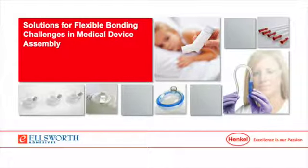For example, we have seen cyanoacrylates demonstrate an increase of beyond 30% of initial strength following 50 to 100 kilogray gamma exposure. That possibly suggests further curing of the adhesive, but we always suggest to end users to determine the effects of sterilization on their device and the cured adhesive.